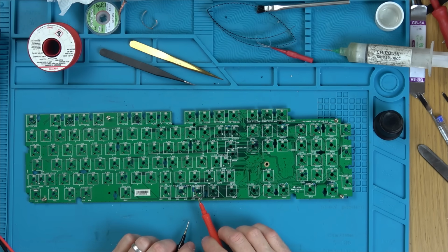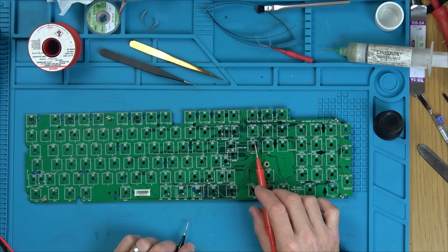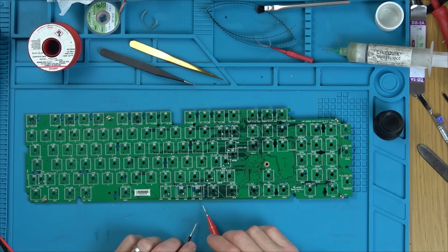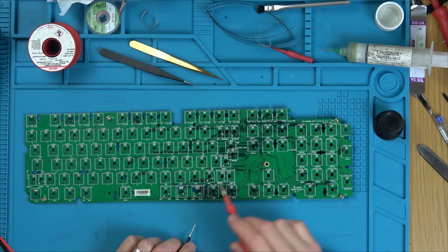I think what I'm going to do is replace the ones that I definitely know are faulty, like this one here, and I'll go across others. If I don't get the green and the red light, I'll replace them. I've got to be careful with the blue, because when I put voltage in, it's going to burn it out. Maybe I could do it with a 100 ohm resistor or something, and maybe that would stop it from burning out. But anyway, I'll do that, because what I'm still hoping is, by replacing one, it might allow the path through, but I don't know how it's been wired.